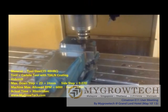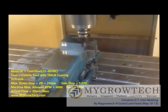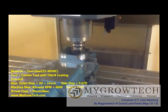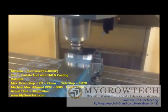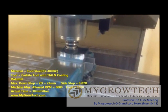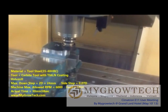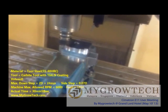And do you hear the vibration sound? That is because the clamping is not nice. The face is not grind. Yeah, the clamping issue, not the machining issue. So part like this, if you have small machines, okay, I don't think you're going to use a big face mill to do it, right? That's why. Part like this, you still need to use a solid end mill. So solid end mill not just for finishing, yeah? It is for roughing also.